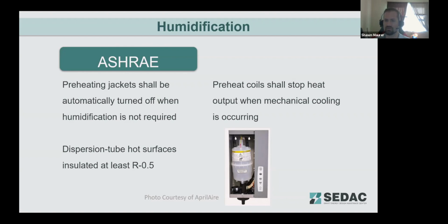Similarly, when you're operating mechanical cooling, preheat coils or freeze protection coils are sometimes used to add a false load to the system to assist in dehumidification. ASHRAE is saying here you cannot do that. They're relying more on controlling the airflow speed across that coil to achieve your dehumidification. So they're forcing you here to look more at the airflow design of the system and rely less on these more energy intensive methods for putting false loads on the cooling system to assist with dehumidification processes.